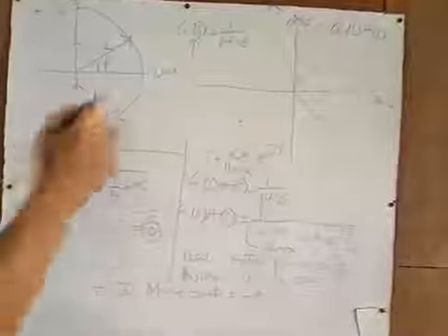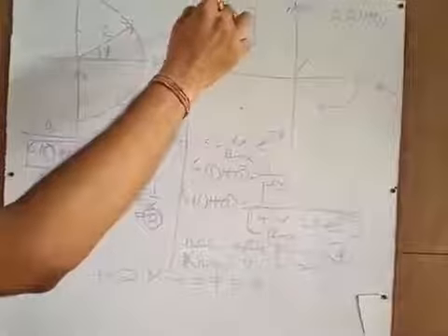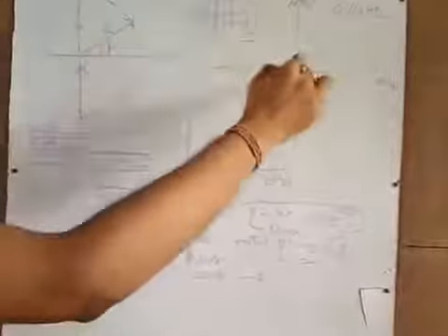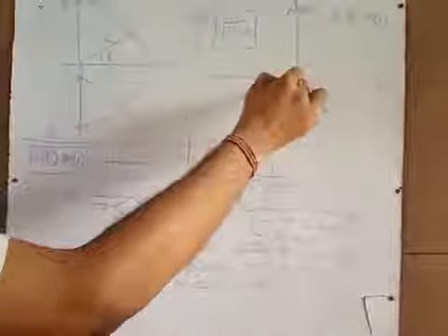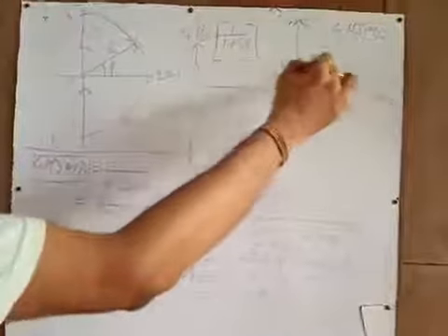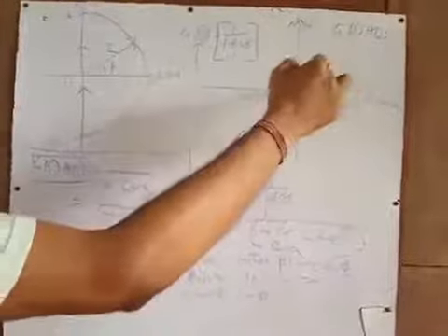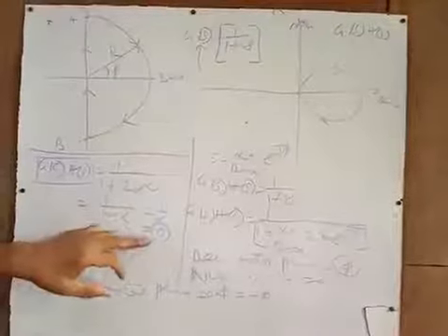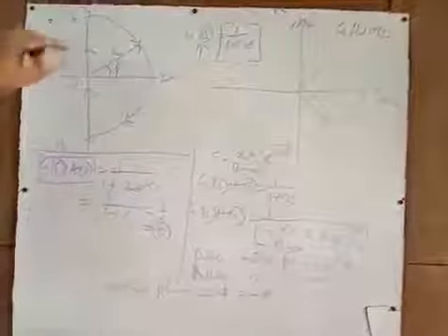So the total Nyquist contour is this, and corresponding to that, if the system is type 0, for this type 0 first order system you get this polar plot. As you see, this part is the mirror image of this part, so this makes a closed path. And you get magnitude 0 when the value of r is equal to infinity.